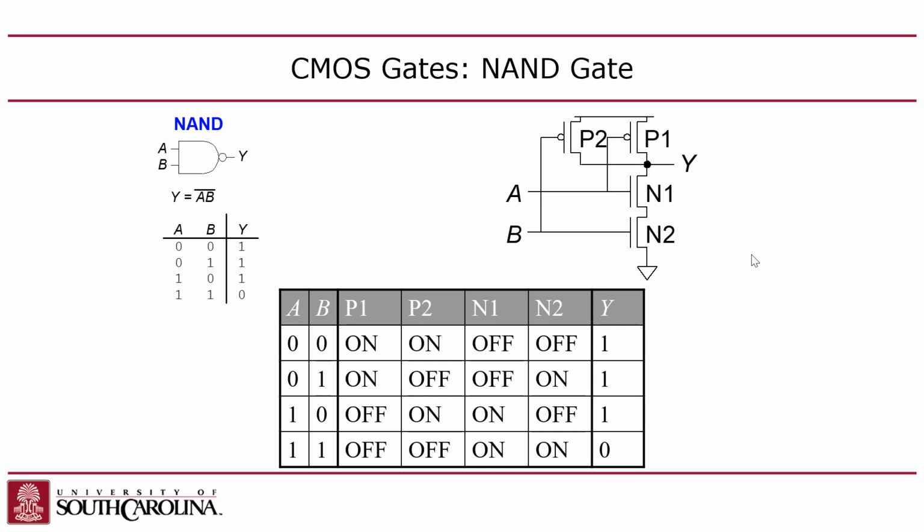However, when you're not switching, there's very little leakage of current, right? When you're not switching the input, in steady state, there's very little current that will go through from VDD, from the power to ground, right? And that's the advantage of CMOS. That's why everyone uses CMOS. It has very little static leakage.